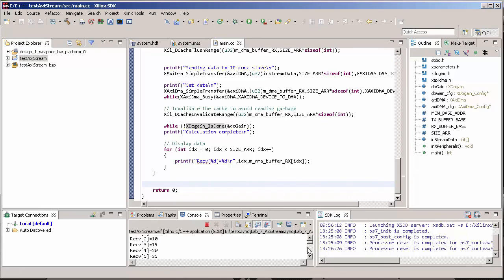So guys, this is enough for today. I hope you understood how to use AXI Stream cores. Remember that in order to use them with a microcontroller, be it the Zynq PS part or even the MicroBlaze, you may need a DMA. The job of the DMA will be to gather data from your main memory, send this data to your IP core and gather the results. And by the way, with a DMA your CPU is not actively doing this, so your CPU can do other stuff while this calculation is being done.